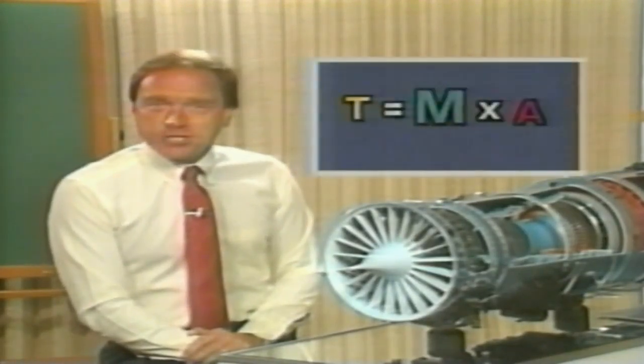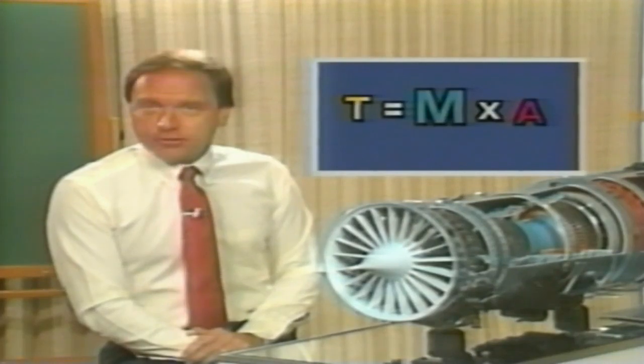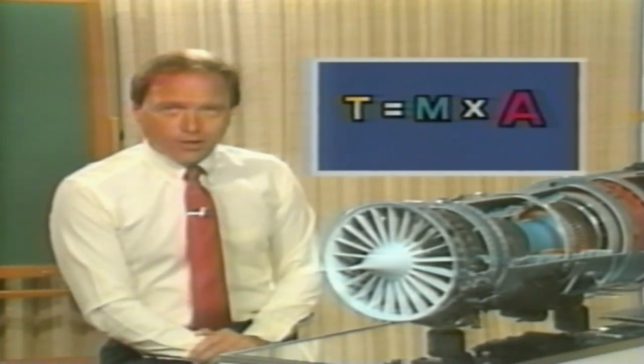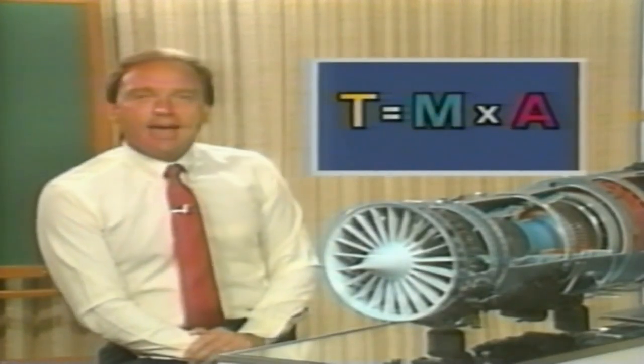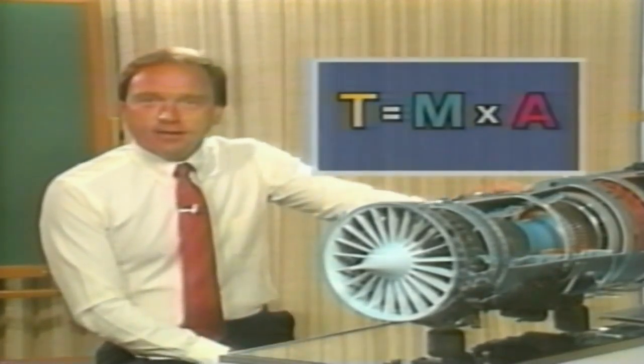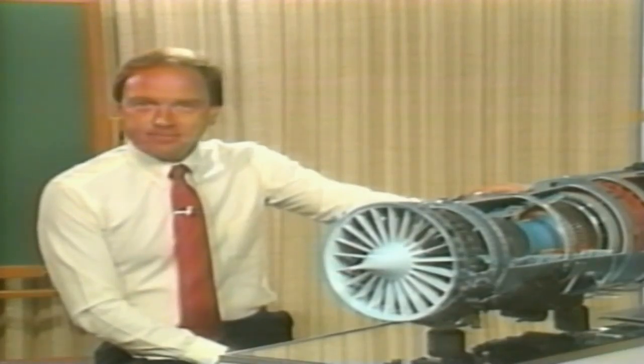These two factors, then, are the main ingredients for thrust. The greater the mass of air flowing through the engine, the greater the thrust. The greater the acceleration of the air, the greater the thrust. Hang on to this T equals M times A concept. We'll find it's a handy tool to help us understand why engines are designed as they are.